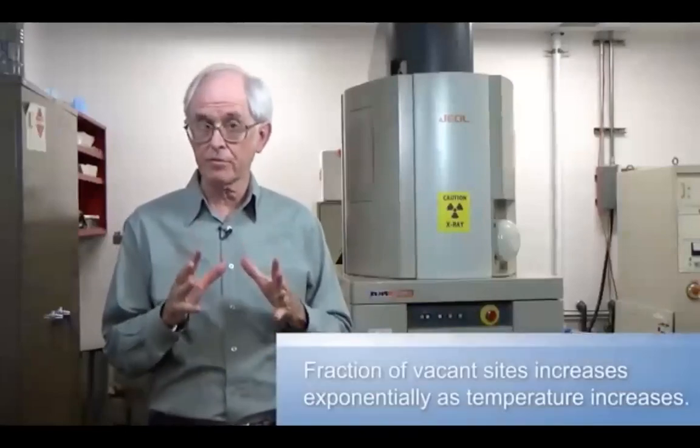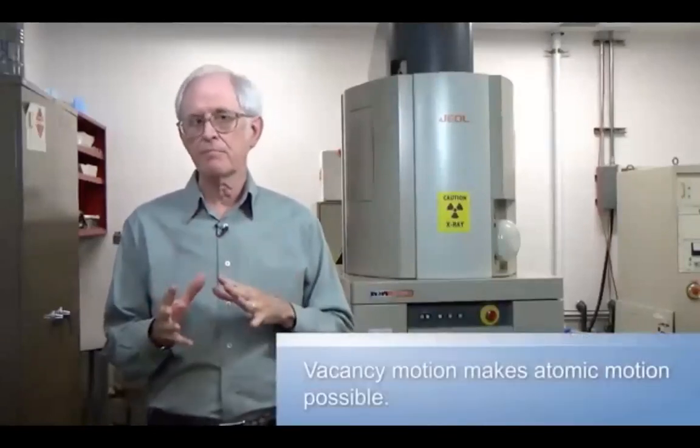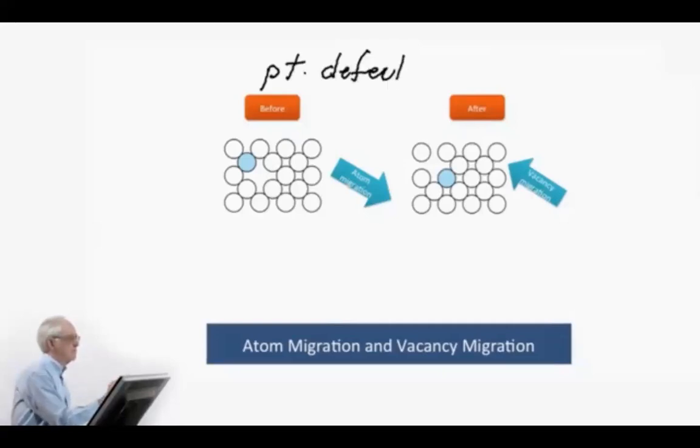And now that we see that the fraction of vacant sites increases exponentially by the Arrhenius relationship as we go to higher temperatures, it's important to appreciate that it's the vacancy motion that makes atomic motion possible. What we'd emphasized when we first talked about point defects, specifically vacancies, is that these are going to be an important part of our understanding of a very practical material parameter in a subsequent lesson, and so here we are. We're now talking about how point defects facilitate solid-state diffusion.